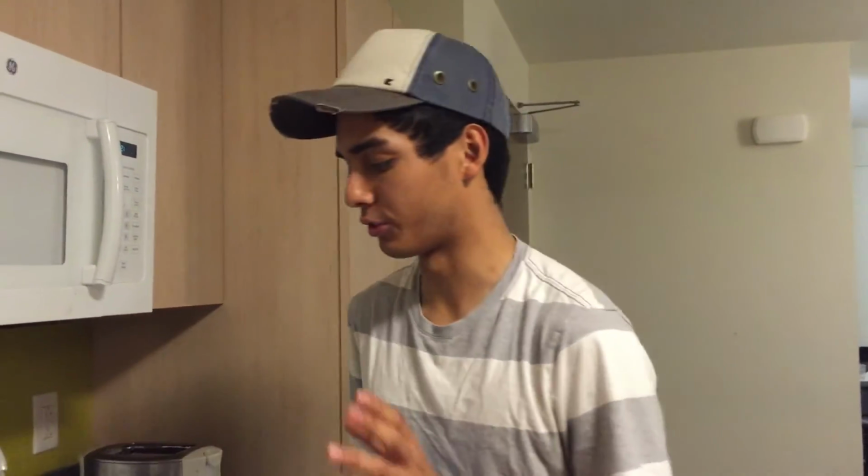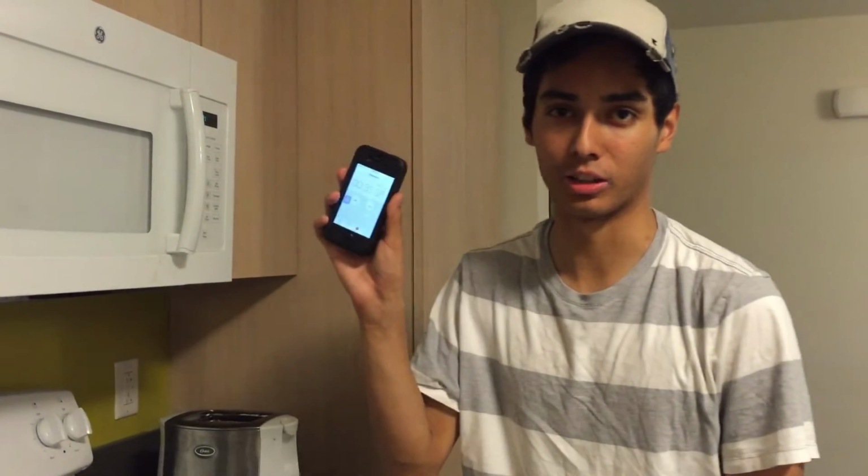So using this concept, we're going to melt an ice cube, evaporate it, and see how long it takes. That will allow us to calculate the power of a stove. You're thinking like an engineer already. Alright, the experiment itself can't be any easier. All you have to do is boil some water and measure how long it takes.